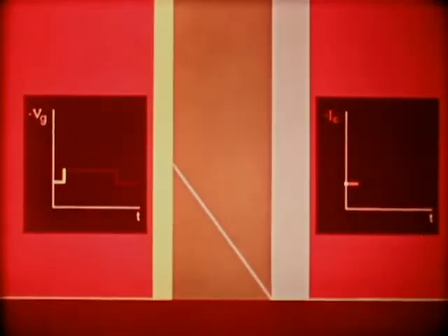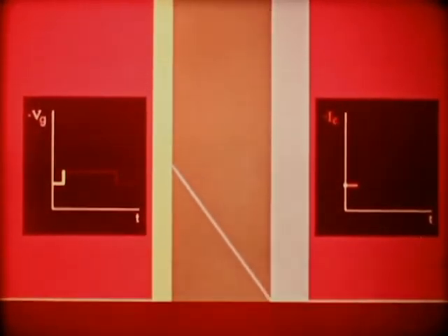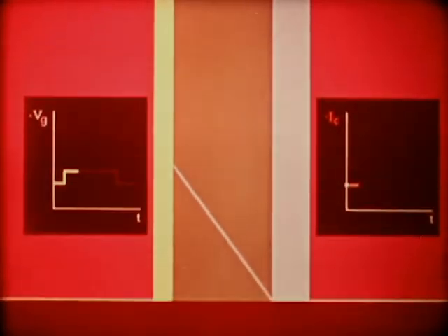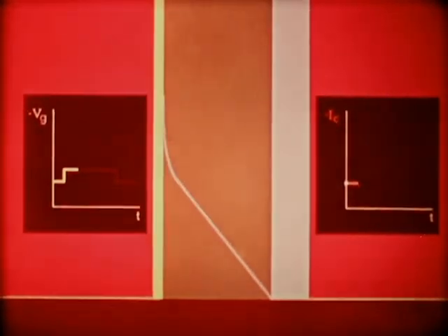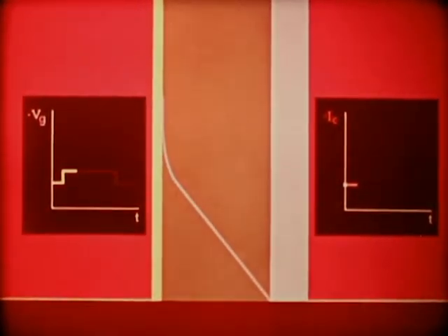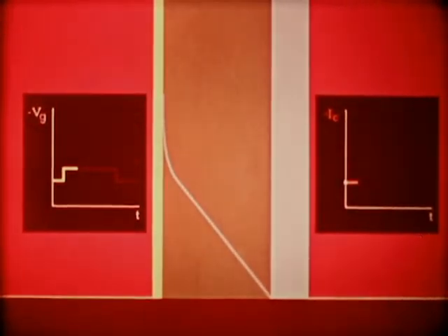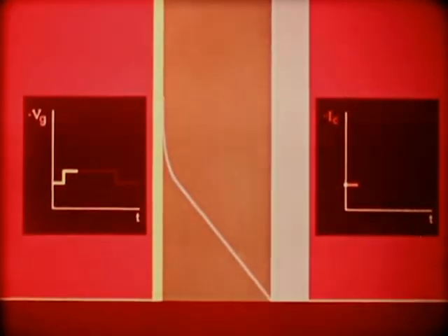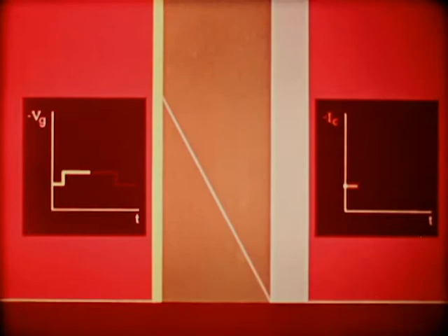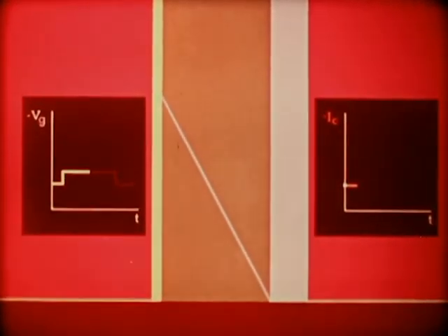This sharp rise occurring at the leading edge of the applied voltage pulse causes the emitter base barrier region to become narrower. Simultaneously, the number of holes in the base near the barrier increases. Consequently, the whole current flowing from the emitter into the base will be temporarily higher, causing the concentration curve to straighten again.